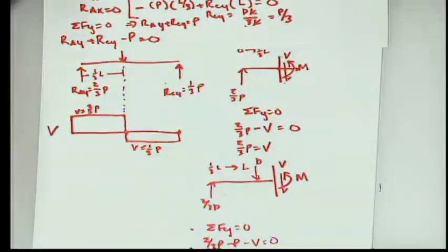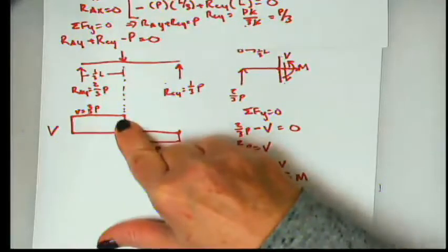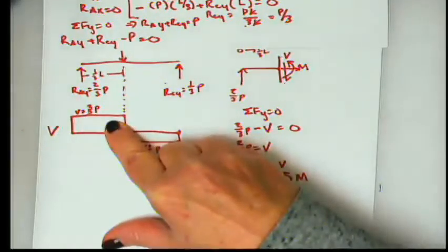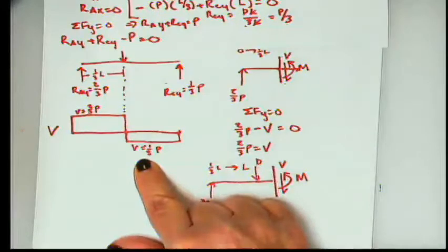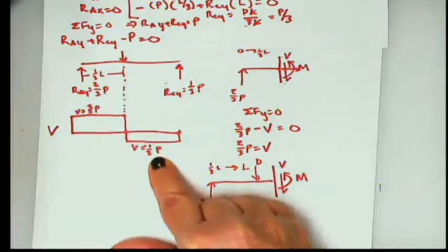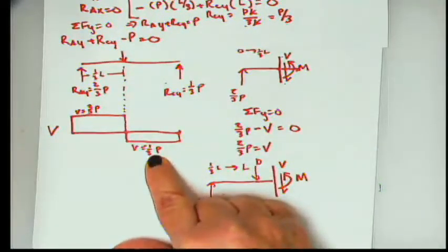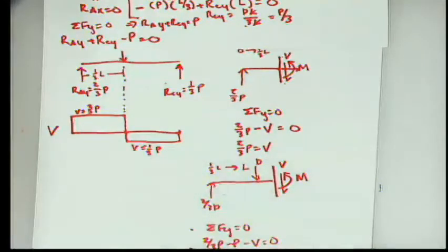You have these discontinuities, and that's really where things are going to fail. Now it also asks, where is the maximum shear? Well, it's everywhere here, isn't it? This is the maximum shear. Now, this is negative, but if the absolute value had been higher, this would be the negative. I mean, it would be the max. So all we're looking for is that maximum value.